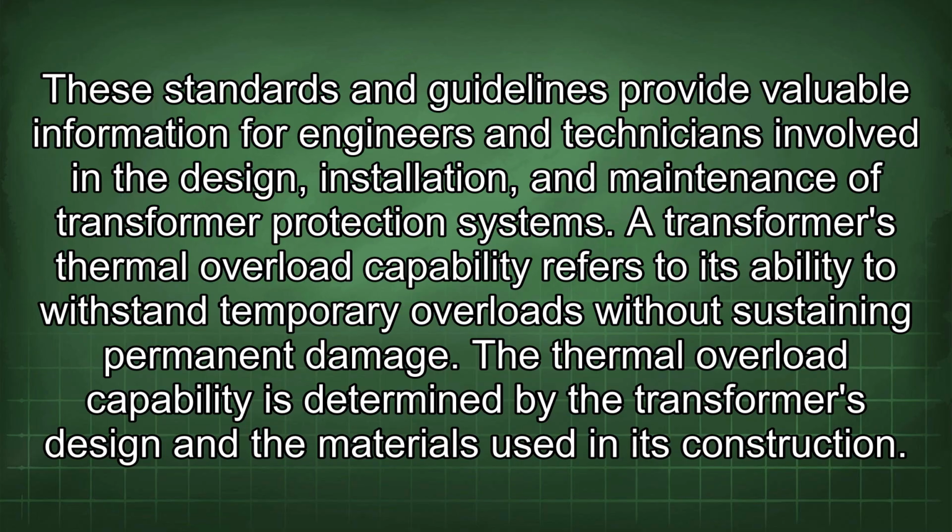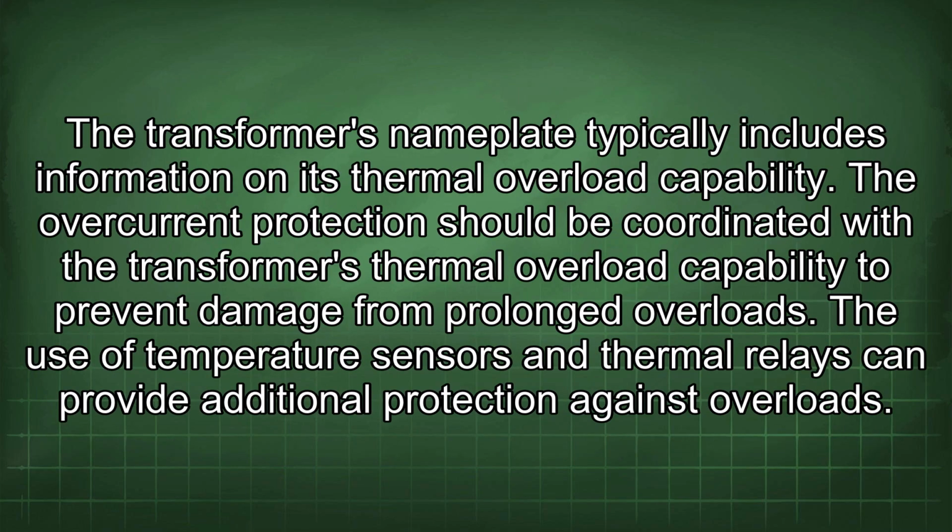A transformer's thermal overload capability refers to its ability to withstand temporary overloads without sustaining permanent damage. The thermal overload capability is determined by the transformer's design and the materials used in its construction. The transformer's nameplate typically includes information on its thermal overload capability. The overcurrent protection should be coordinated with the transformer's thermal overload capability to prevent damage from prolonged overloads.